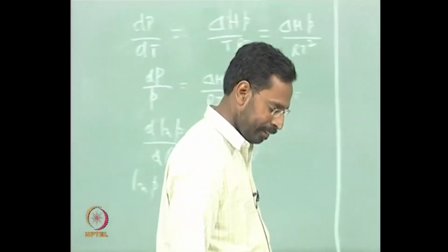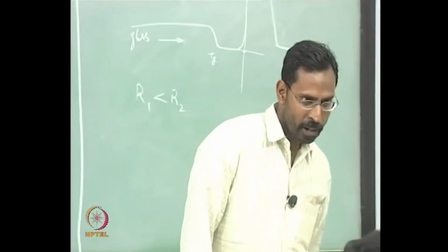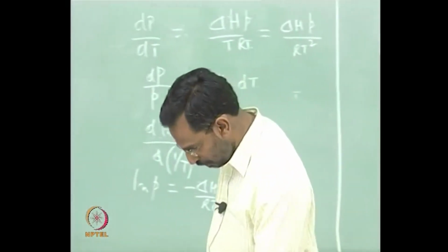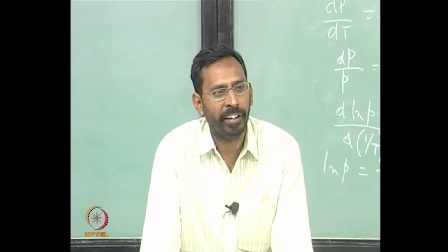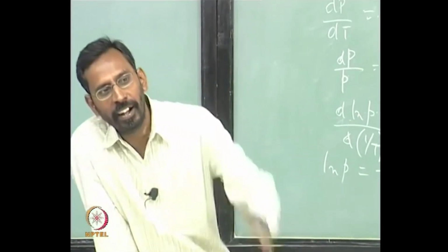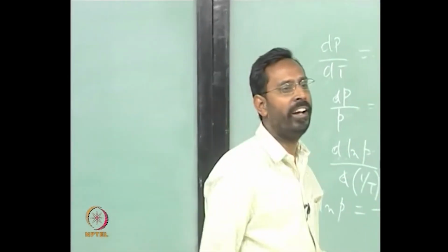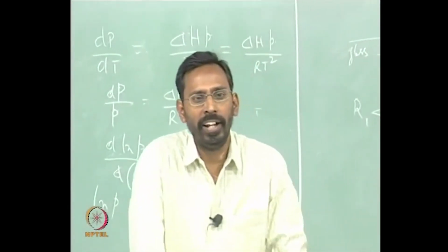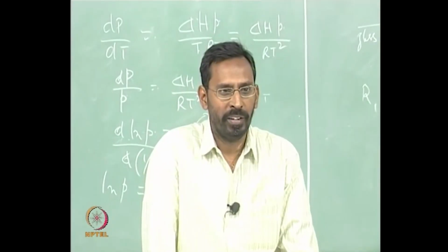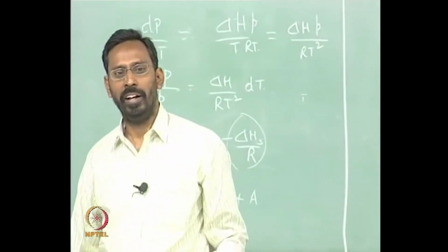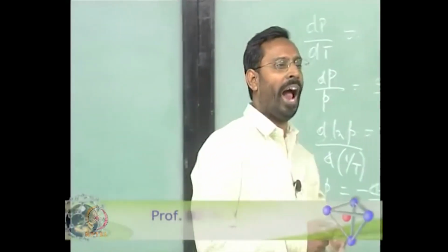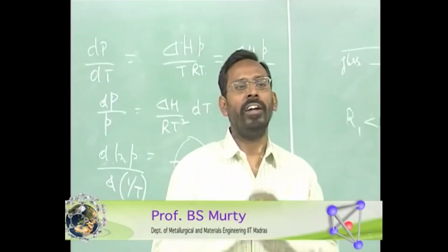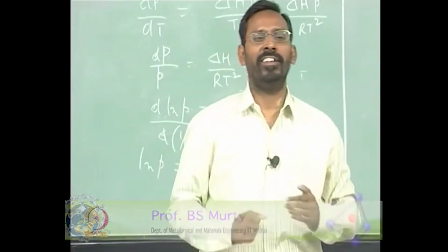The kinetics are the transformation rates. No, to get uniformity it will take. Yes. Any more arguments? You are saying something, Anisha. It is basically the inertia of the system. Whenever you heat a sample at a higher rate, the sample does not transform at its equilibrium transformation temperature, and it transforms at a temperature higher than its equilibrium transformation temperature.